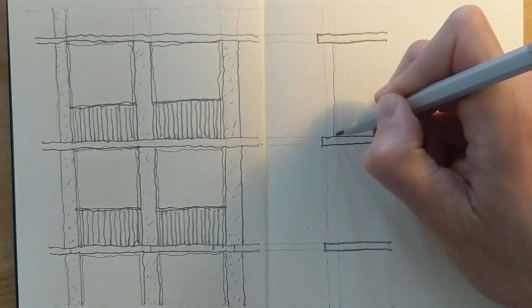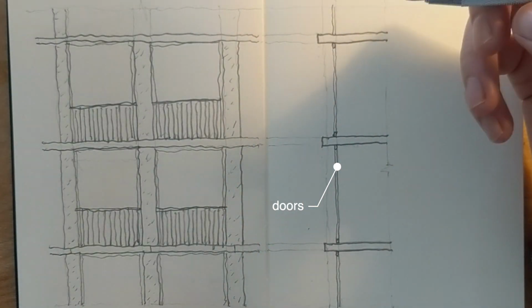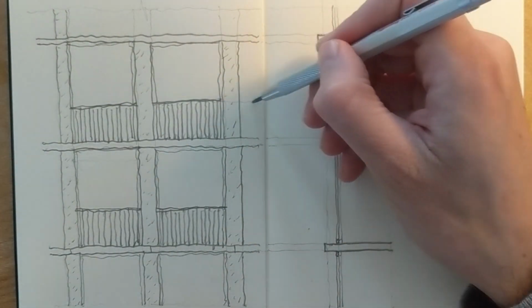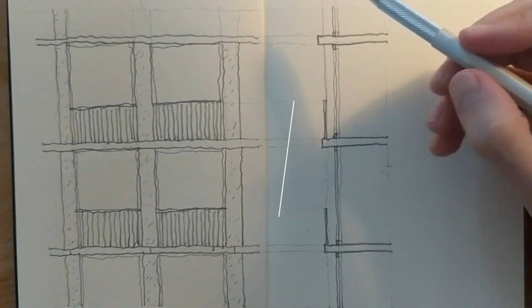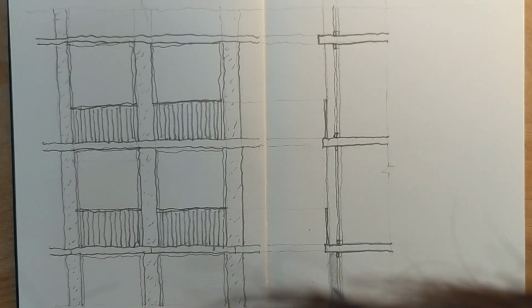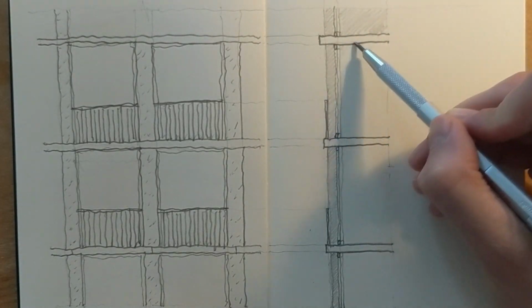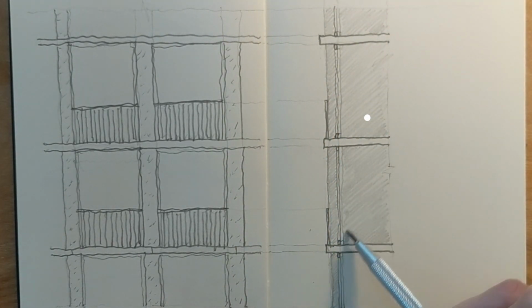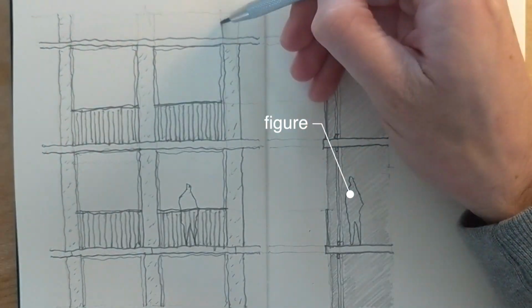The sliding doors are added. We can see how they're recessed, which helps to create the balcony spaces. Again, I use light projection lines from the elevation to show the guardrails at the right height. Shading the face of the columns and the interior walls adds some depth to the drawing. And by adding a figure to both the elevation and section, we can get a better sense of the scale